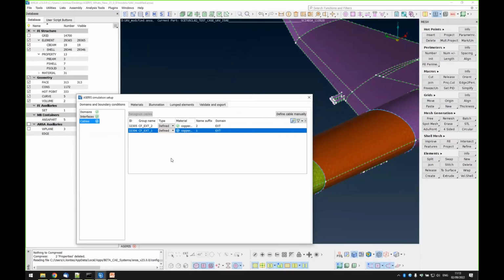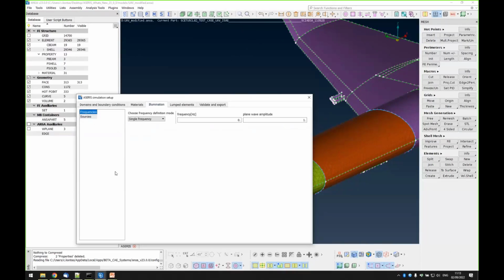And let's go to the illumination. So I have chosen this model to have a mesh length that corresponds to 300 megahertz. Quick note that usually in boundary element methods, you need the mesh length to be lambda over 10 or lambda over 5, around this range, to be accurate enough. It's best to have lambda over 10, where lambda is the wavelength. And another note is that the only mesh that is supported is triangular. You cannot have quad elements here.